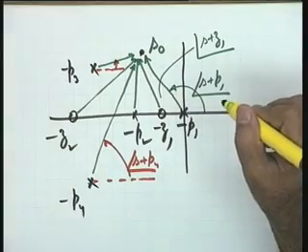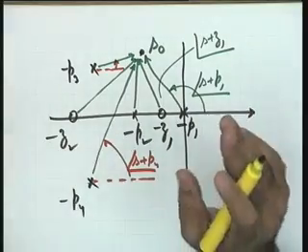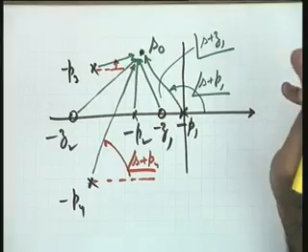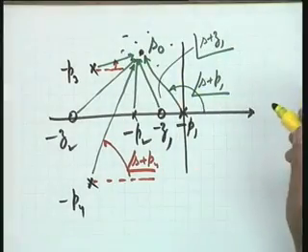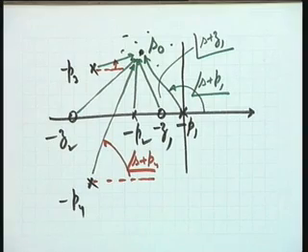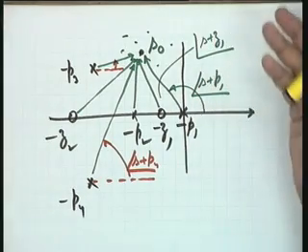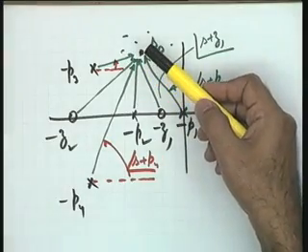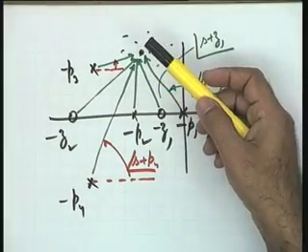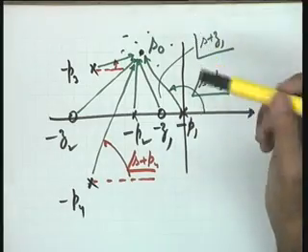If it does not, then depending upon the deviation you are getting from 180 degrees, you can take your trial points here and there and satisfy this. Now you can definitely curse me if I say that this is the only method of root locus plot I will give you. Instead of going for this method, naturally you will like to go to the computer and make the computer give you all the roots.